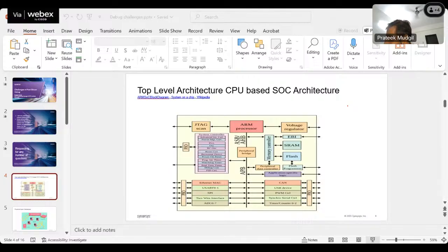So what they will do, let us say data is fixed, right? And clock is this, and there is a skew coming. So the analog block will push the clock this side and this side and try to see how much data is sampled properly. So this is a push of clocks, you can say. Let us say the clock is being pushed by the receiver by X amount of skew, right? And vice versa also, in the negative direction, it found that in this window it was able to sample the data properly, right? So this is the eye, and the more the eye width, the better we are at sampling the data, right? So we are trying to get the maximum eye.